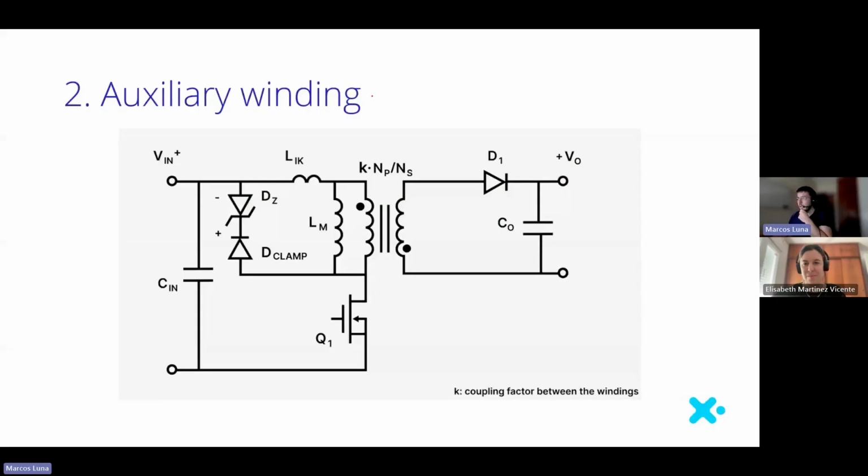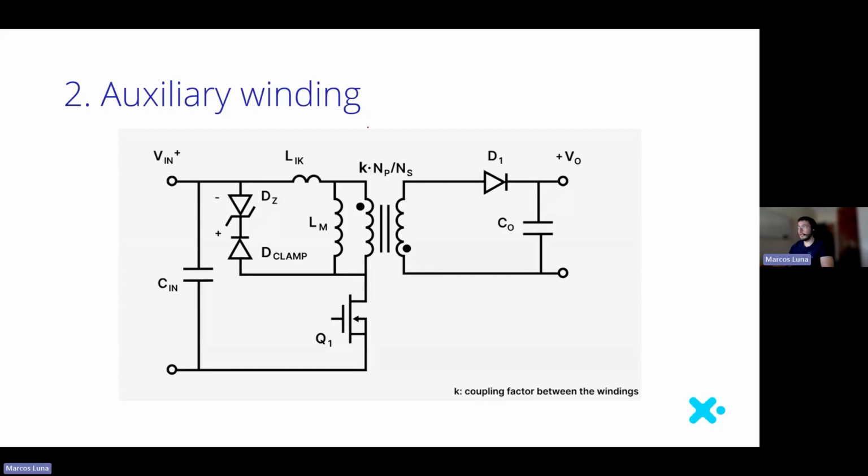Okay, thank you, Ellie. Hello, everyone again, and thanks for joining today's webinar. Today I'm very excited about the topic, because converters and flyback transformer design are a very particular design. Most of you probably know it's physically a transformer, but it works more as an inductor, storing energy in the primary side and then transferring it to the secondary side.